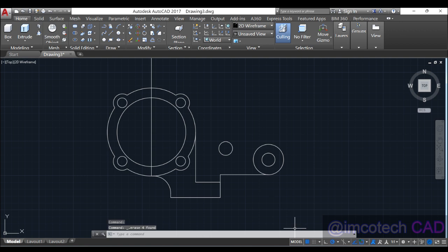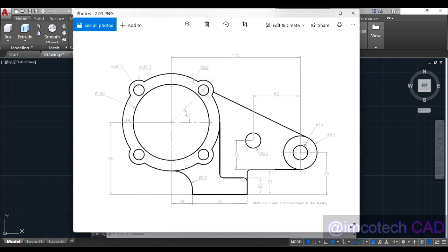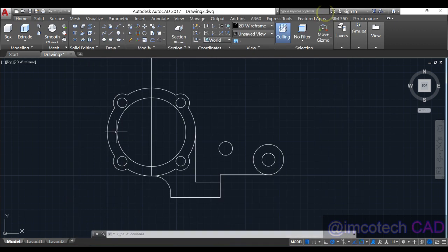The final step is the closing line. You can call it closing remark. So this particular line, we're going to draw it at tangential position to this circle and also at tangential position to the inner circle. But as you can see, we don't have that inner circle, right? So let's return it back. Just use center radius so you don't stress yourself, and drop it right there at the center.